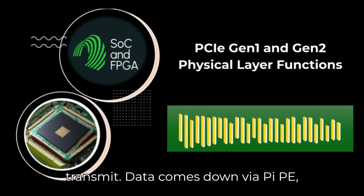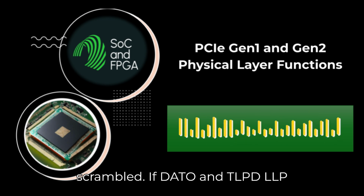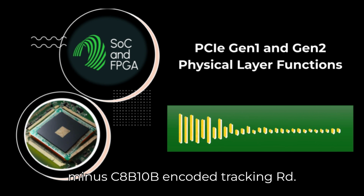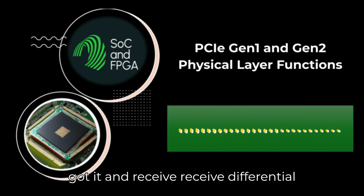Data comes down via PCIe, maybe byte striped across lanes, scrambled. If data in TLP-DLLP, legacy 8B10B encoded, tracking RD, serialized by SerDes, driven differentially, maybe with de-emphasis. Got it. And receive?